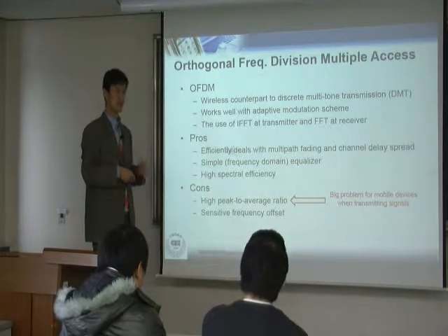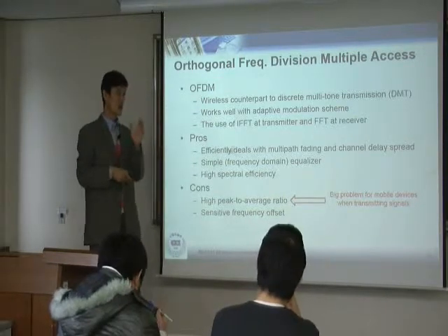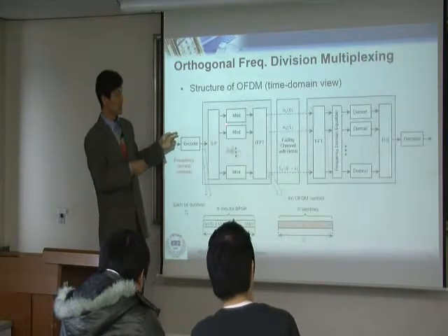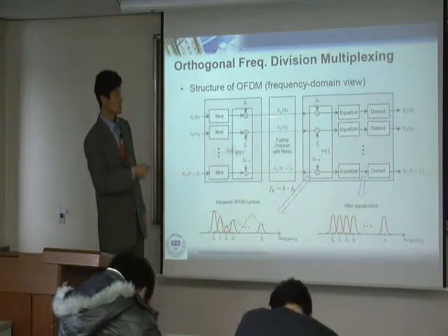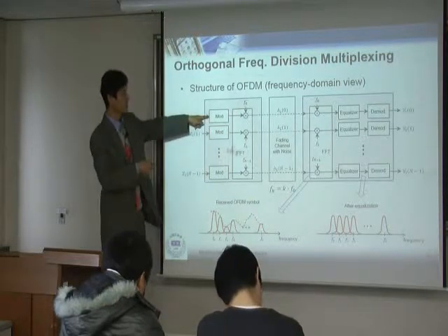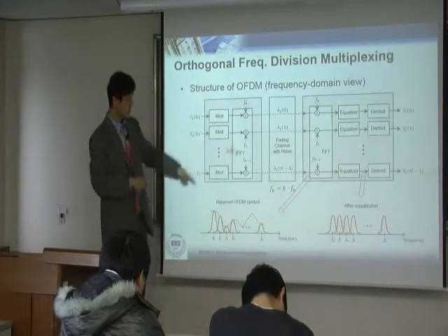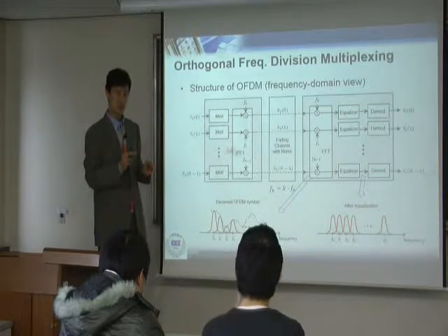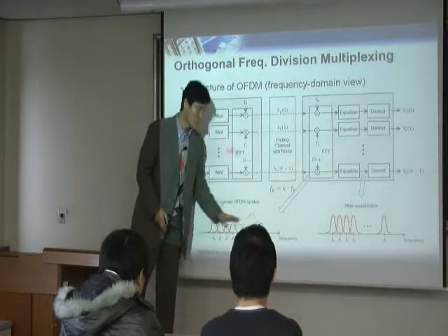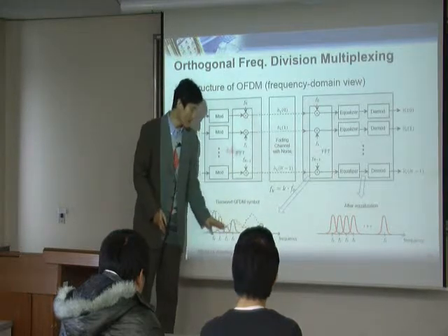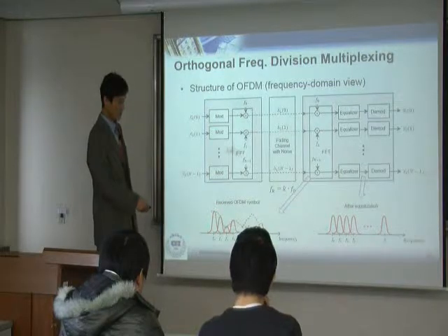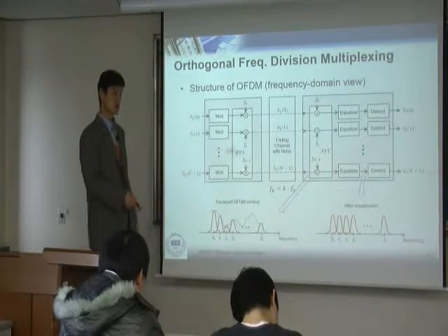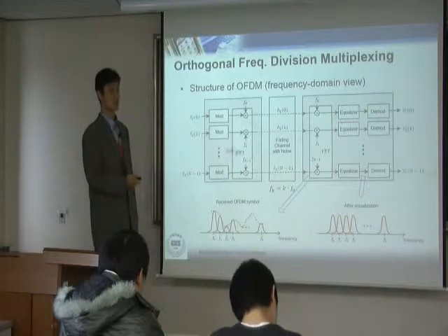The second reason, a more important reason, is that each subcarrier now we can treat independently. That's what we mentioned. It is simply a parallel of multiple subcarriers. Each subcarrier is independent, and for each subcarrier you can use a different modulation and treat it differently depending on the channel response. In single carrier, that's not possible. You just transmit the same thing, same power, everything the same, although you have a fluctuation in the frequency response. But in OFDM, you do it this way. So that is another fundamental reason why this is much more spectrally efficient.